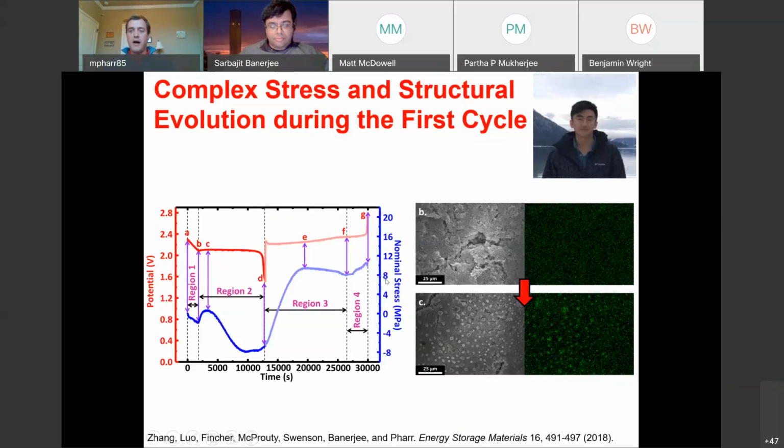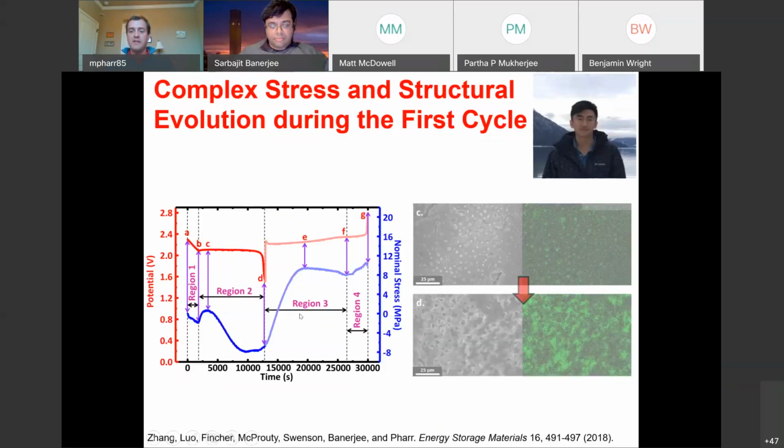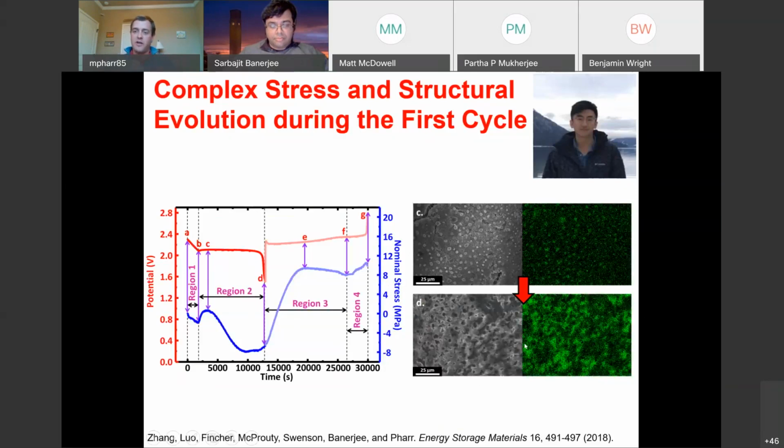Then we start to deposit the lithium sulfur product back onto the carbon, and this forms these discrete points or islands here initially. And eventually these things densify and push on each other. So if you're familiar with thin film nucleation and growth type processes, you see the signatures of that in our stress signals, compression, then tension, then compression again. After a lot of lithiation, we actually get this flat region around 10,000 seconds or so in the plot here that may be indicative of plasticity.